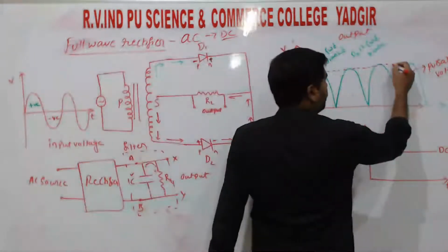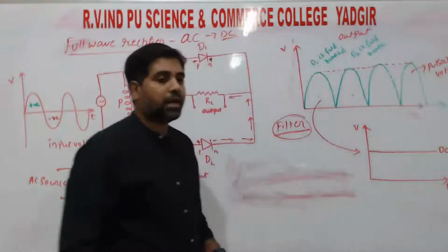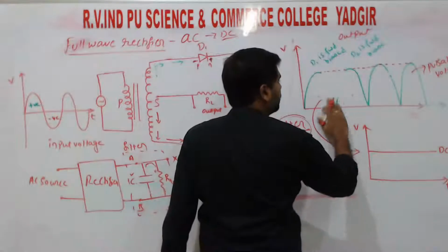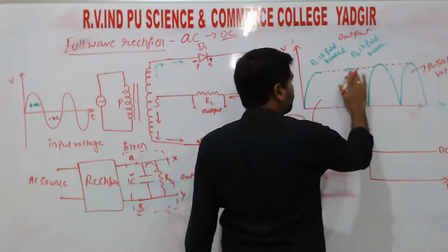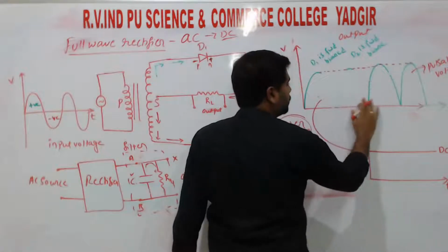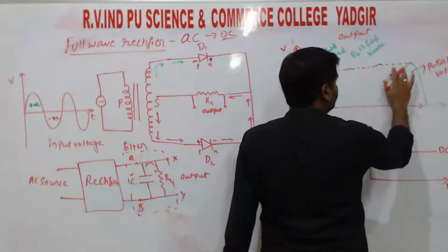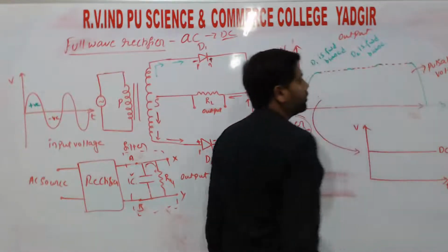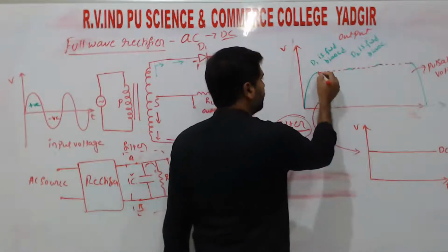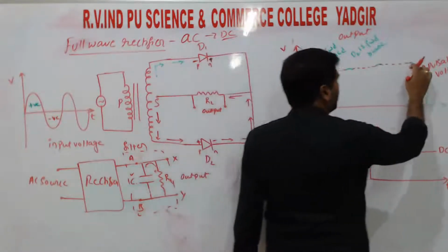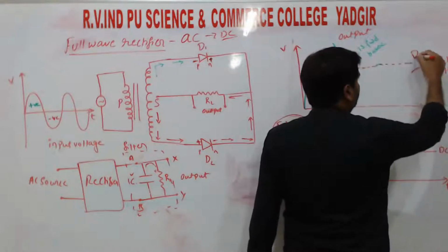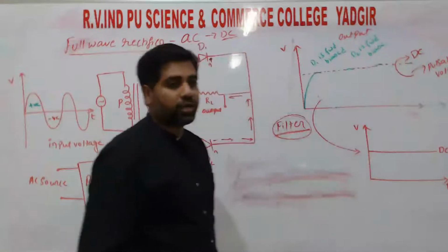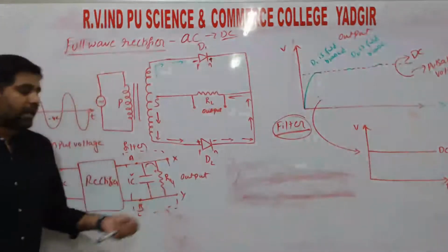So this process will continue like this, right? From this we can eliminate this value, that is the decreasing of the voltage is removed by using the capacitor, right? That one we call the filter. So we get constant current, which we call direct current, that is DC current. We are converting the pulsating voltage into the DC voltage, that is direct voltage or direct current.